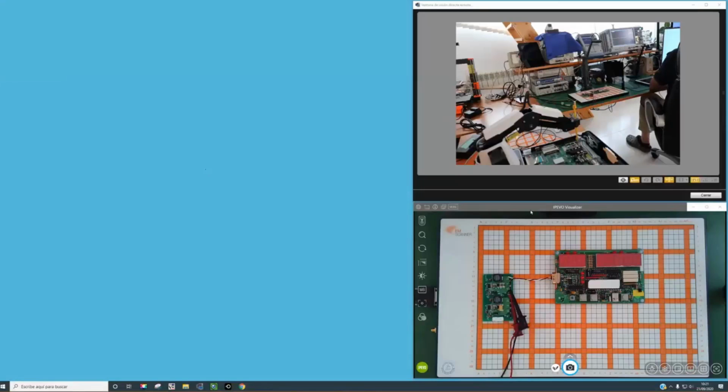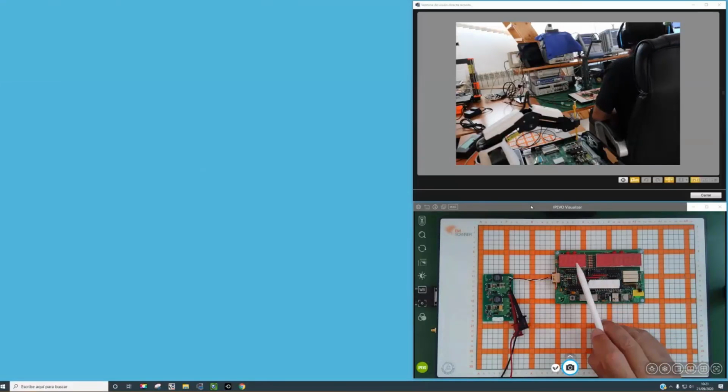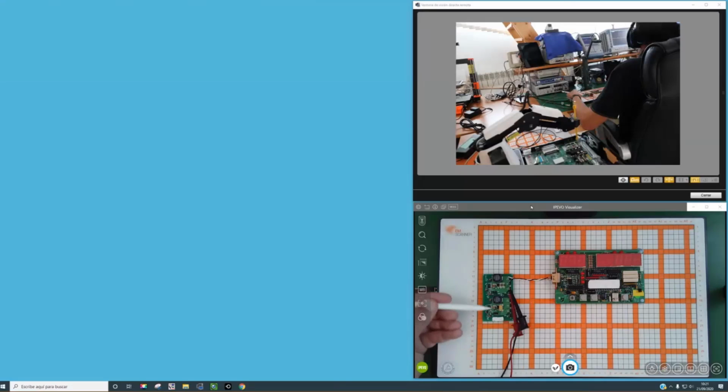Okay, let's go to the screen and let me show you the PCB I will be using. This is the PCB I am going to use in my setup. This is a PCB where I have a display, a microcontroller, several keys, some kind of logic, and a connector for the power supply. The power supply is 5 volts and it's coming from this PC board. This is a small PC board with two DC-DC converters. This is a 5 volts DC-DC converter. This is a 12 volts DC-DC converter. And we'll be using only the 5 volts power converter.